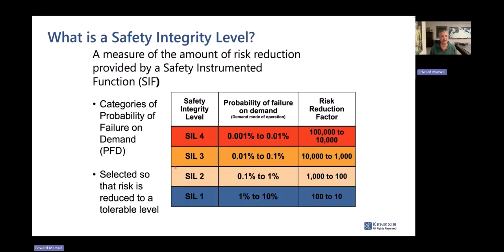protection, that prevention. So not that anyone needs another tutorial on what the SIL levels are, but SIL levels are defined as order of magnitude probability of failure on demand. SIL 1 being the lowest, SIL 4 being the highest, where SIL 1 has a probability of failure between 10% and 1%, and then SIL 2, 1% to 0.1%, order of magnitude step changes for each SIL number.